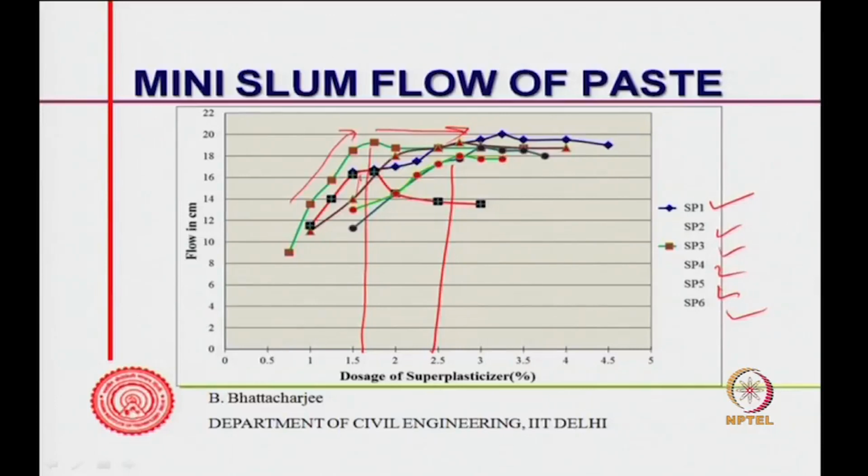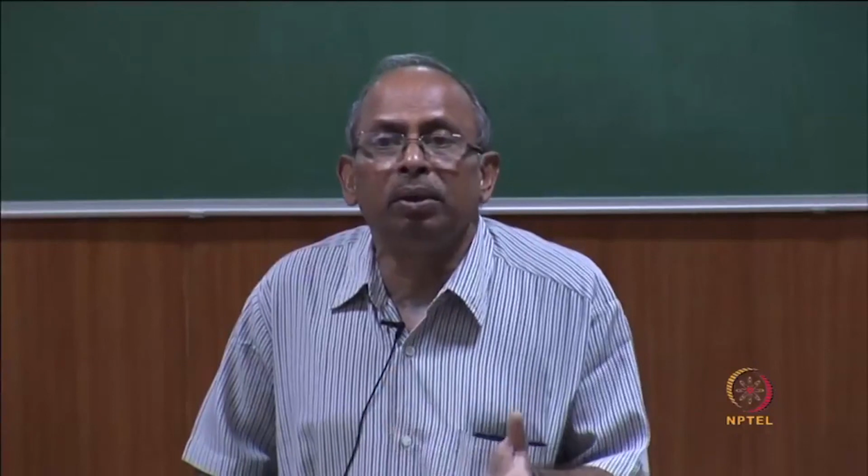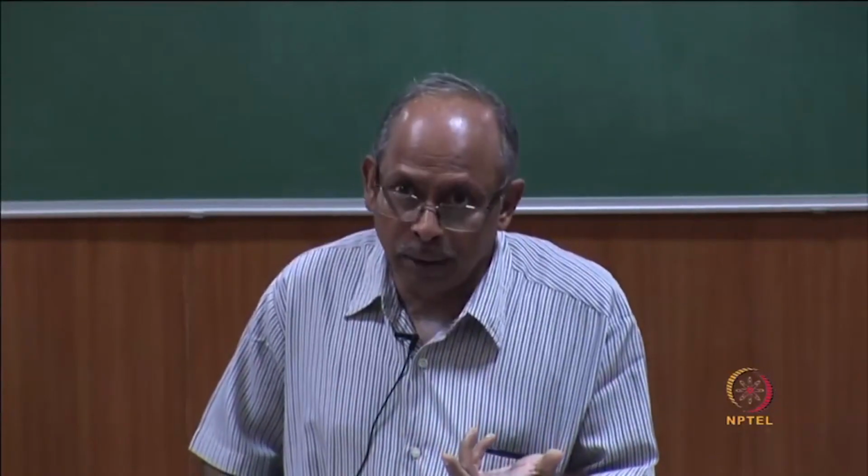Now, this optimal dose is the maximum dose that you can apply, because beyond this, addition of superplasticizer does not show any further improvement in flow.